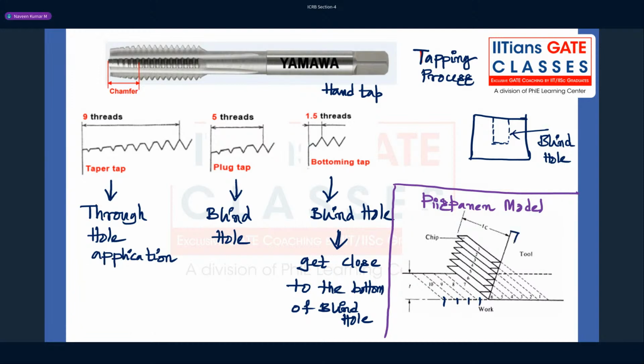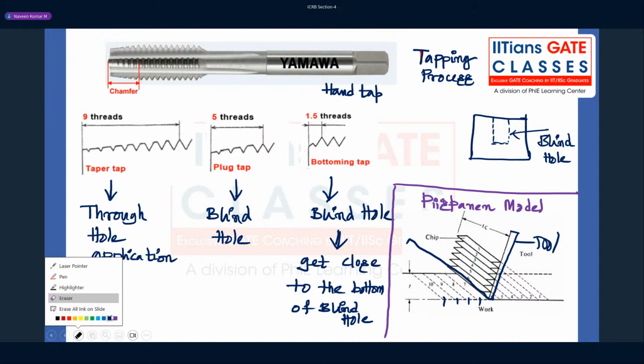And suddenly you have put some kind of an obstruction here, and that is what the tool is here. Now what happens? The deck of cards starts moving in the direction of the face of the tool, and you see the direction is being changed at this angle. It can happen at any angle. Don't think this is perpendicular. You might ask, sir, it is like this. No, it is not perpendicular. So it can take any angle, and that angle is what is called the shear angle.